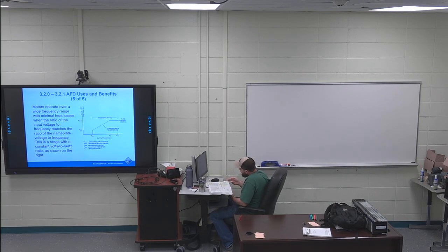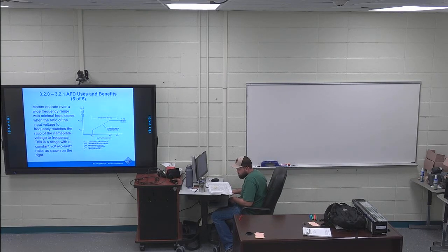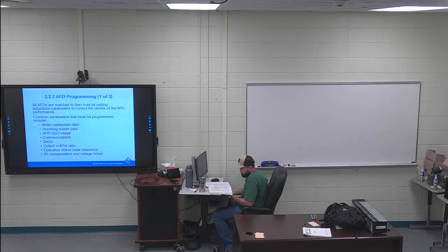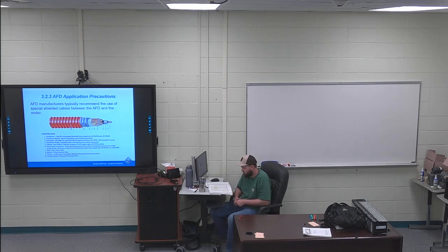They go through programming. I don't have anything highlighting programming, but you will program a VFD in the lab. 3.2.3, AFD application precautions. First bullet point's highlighted. Any fan-cooled motor is at risk of overheating and failure when the AFD operates at slower speeds, 50% of its base speed or less, for more than a few minutes. To prevent this, an externally powered fan must be used to maintain the needed cooling airflow. This is particularly true if the motor has a Class F temperature rise or a 1.0 service factor.